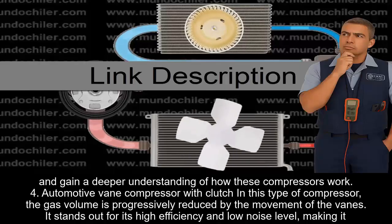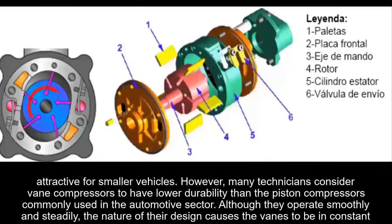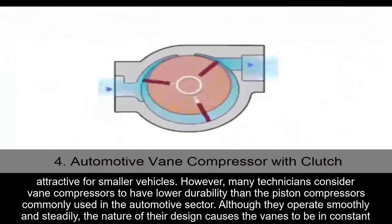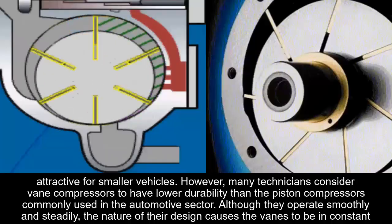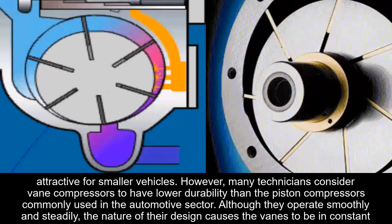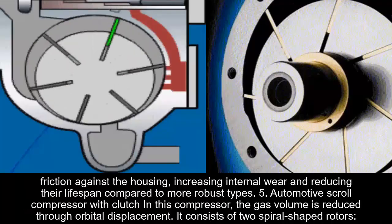4. Automotive vane compressor with clutch. In this type of compressor, the gas volume is progressively reduced by the movement of the vanes. It stands out for its high efficiency and low noise level, making it attractive for smaller vehicles. However, many technicians consider vane compressors to have lower durability than piston compressors commonly used in the automotive sector. Although they operate smoothly and steadily, the nature of their design causes the vanes to be in constant friction against the housing, increasing internal wear and reducing their lifespan compared to more robust types.